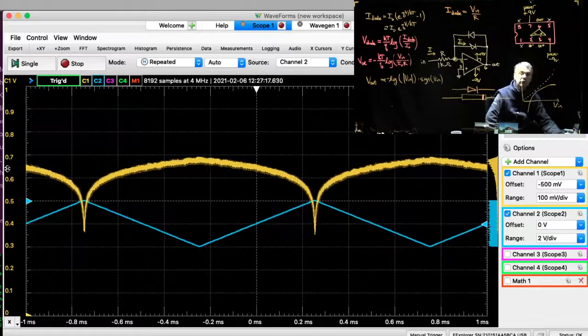You remember when an ordinary diode is fully on, its voltage is between 6 and 7 tenths of a volt. We call it a diode drop. So that kind of makes sense. For the part where it's most on, we get about 0.65 volts here. And then because of that logarithmic behavior, as the argument gets bigger and bigger, the slope of the logarithm function gets smaller. So this is this flat portion here. And again, we call this the barn roof distortion. It kind of looks like a barn roof or a gambrel style roof. And then down here, where the input signal is small in magnitude, the slope of the logarithm function is quite big. Again, this is like the sides of that barn roof. So the top of the barn roof, the sides of the barn roof.